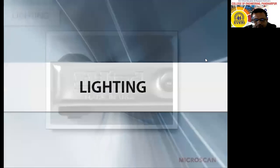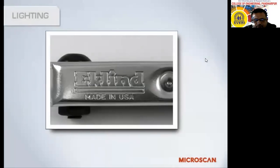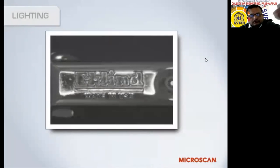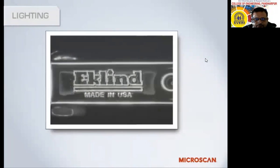The type and position of a light should be carefully selected to maximize contrast of the features you plan to inspect and minimize contrast of everything else. This is like an electrical engineer setting up a system to give a high signal-to-noise ratio. You're trying to make the pieces you need to see or need to measure very clear, and you want all the other items in the image as invisible as possible.